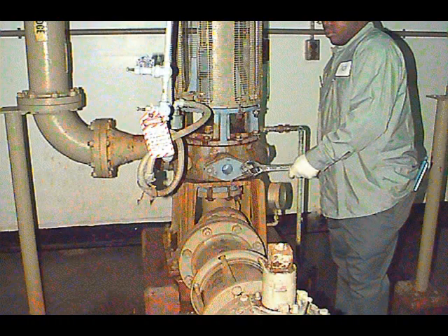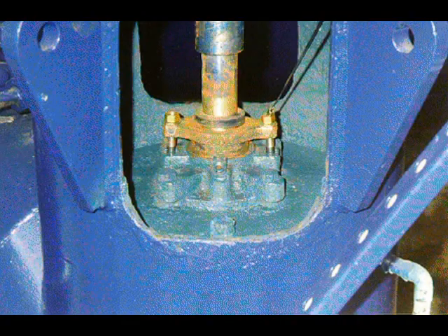Drain the pump by loosening the bolts on the handhole cover. Do not remove the bolts completely until the pump stops draining and the shutoff valves are holding. Remove the packing gland nuts and/or bolts and remove glands. These are usually split for removal. If the packing gland is not split, it has to be backed off on the shaft. Be sure to provide room for removal and replacement of packing.